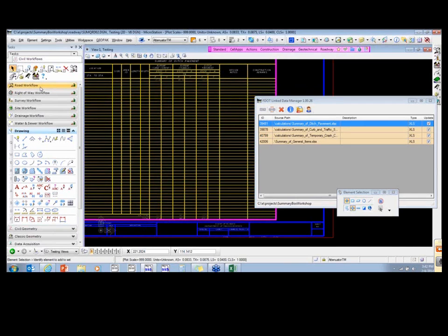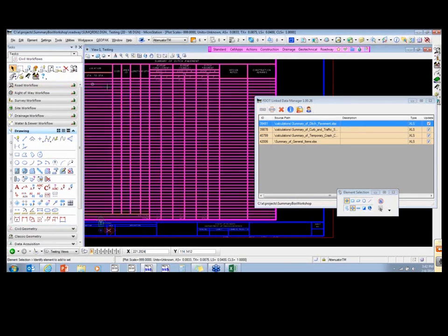Okay, next. Do the structures quantity summary tables go into the structures component plan set or are they included in the roadway summary section? If there is a structures component, the summary sheets go in the structures component. If you've got a roadway and a structures component, then you're going to have the structures key sheet, and then you're going to see the summary of structure quantity sheet right behind the key sheet. If you do not have a roadway component, then obviously yes, it goes in there, but you'll have the summary of pay items sheet in between.